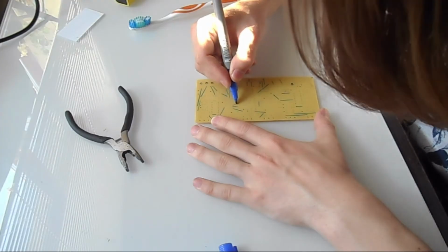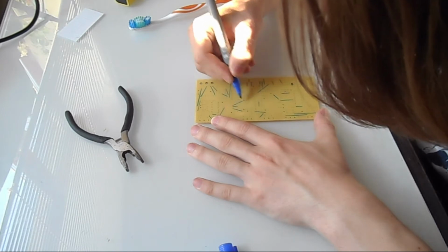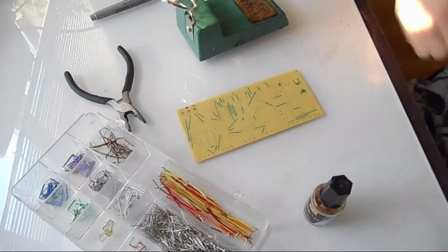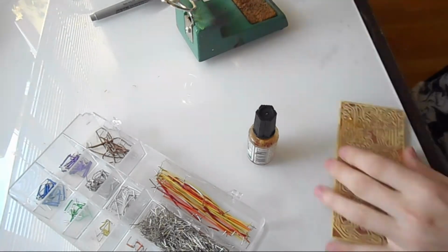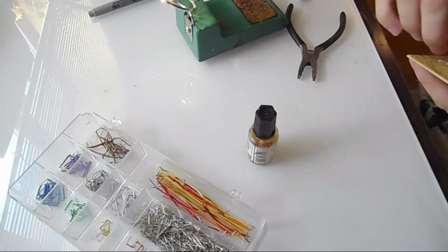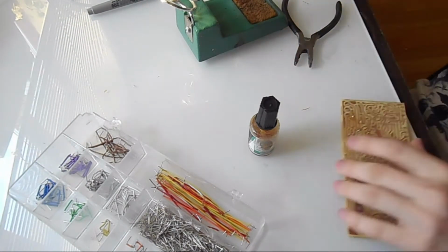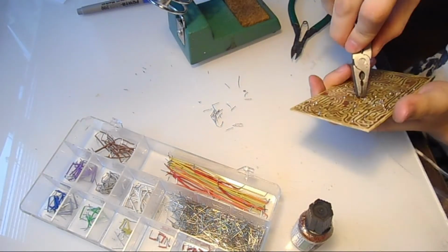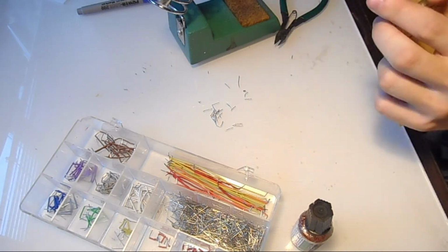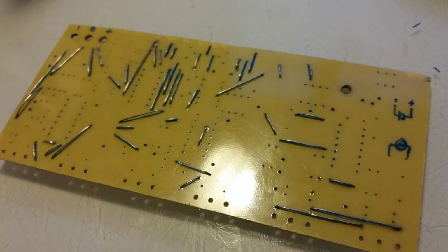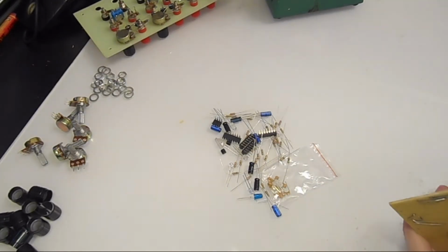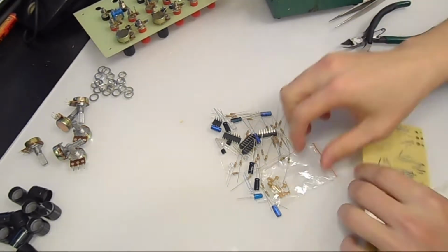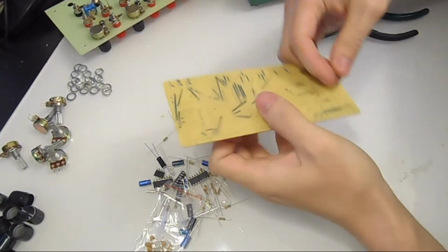I start assembling it by tracing all the jumpers on the PCB with a marker. I solder the board from the least sticking out parts to the tallest ones, and the jumpers are simply pieces of uninsulated copper wire, so they go first. I use the remains of resistors and diodes. After that, I put all the diodes and resistors in place and solder them in. They are the second least tall components on the board.